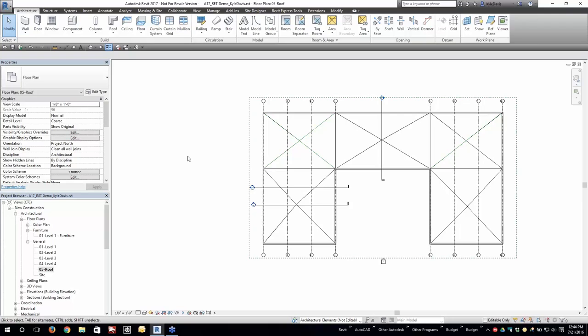One question that just came in: is there a way to specify the slope instead of points? Unfortunately, no, there is not. I know that's been a big one: can I specify the slope of the taper? Unfortunately, it is based on measurements instead of giving it a 1/4 inch slope or a 1/8 inch slope or something like that. So currently the only way to do it is by inches, so you have to know that measurement.